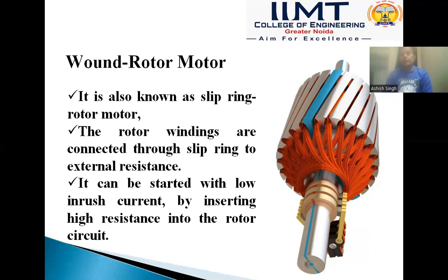What is inrush current? At the time of starting, when we start three-phase induction motor, the back EMF on the rotor is zero. So at the time of starting, induction motor takes high starting current that is called inrush current, and that is up to 4 to 8 times higher than its rated current. So to reduce that high inrush current, we are using high resistance in the rotor circuit. We connect high resistance into the rotor circuit with the help of